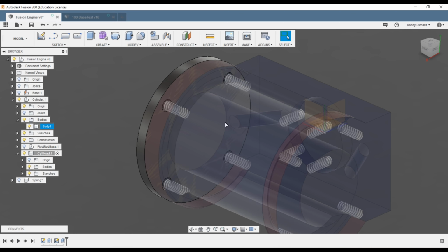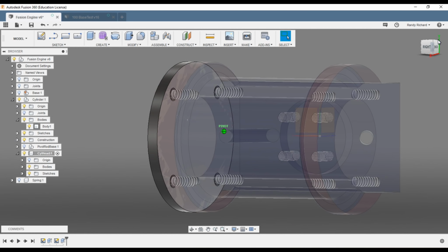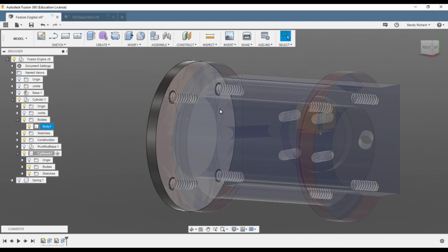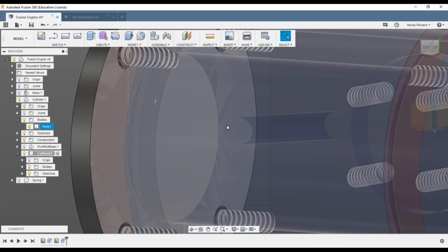And the head is sitting on the cylinder, and how are we going to do that? Well, it's the same as the bore size, and we see our angled port coming into the cylinder, and we don't want to cover up the edge of that. It's going to affect our piston because of clearances in the cylinder. But we want to come in a little bit, maybe 20, 30 thousandths. We'll see how much room we have there.